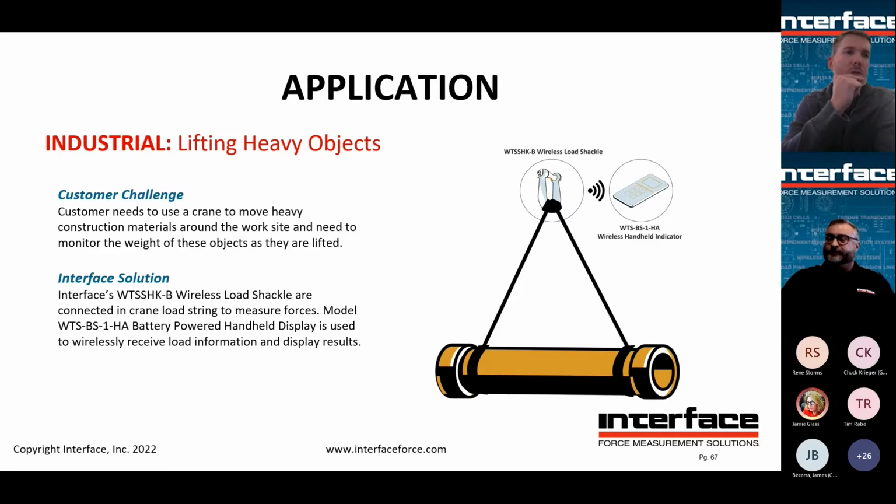And lastly, as opposed to a single point here, if you're lifting a container, say you're lifting it at 4 points, it'll also give you the center of gravity to make sure it is loaded correctly, so that when you are picking it up, it isn't going to slosh around or put too much load on one corner.